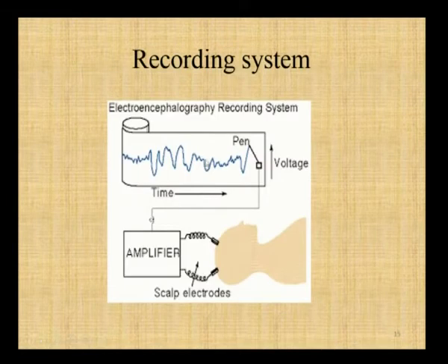Then the recording system, it is a very simple recording system. Here we have a patient, and electrodes are placed on the skull. Here we are using only 2 positions of electrodes. Then it is connected to the amplifier circuit. This amplifier circuit collects the signals from the electrodes and passes them into the output recording system. In the output recorder we will be using a pen shaped writer. Because of that, the signal produced by this measurement will decide the shape of the waveform.